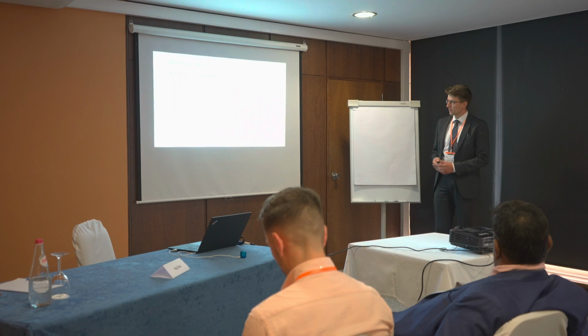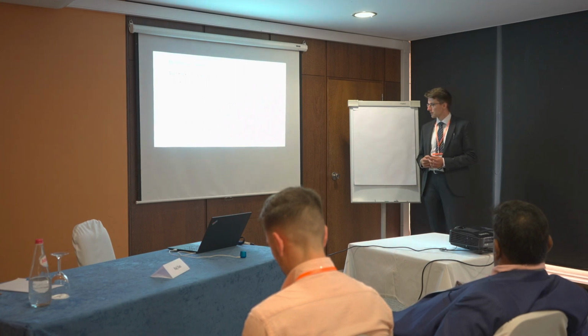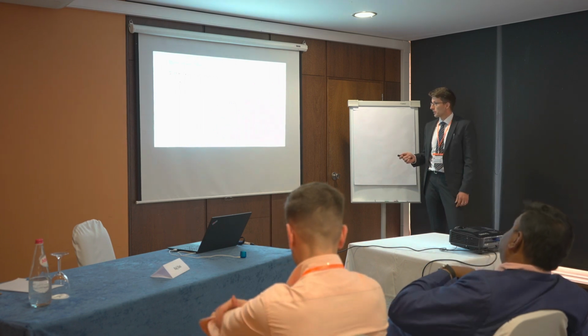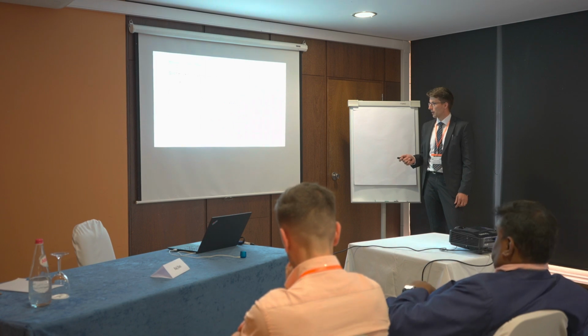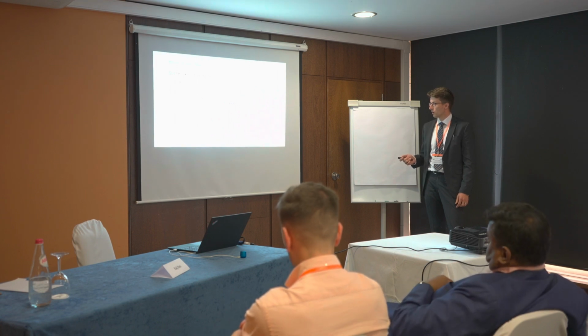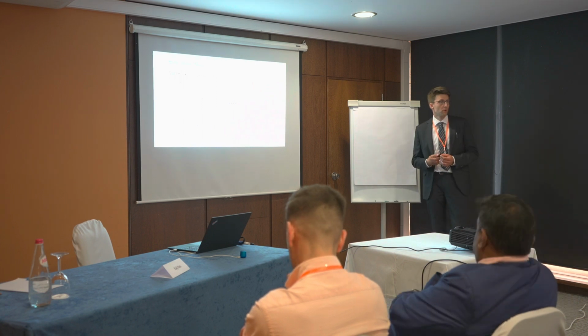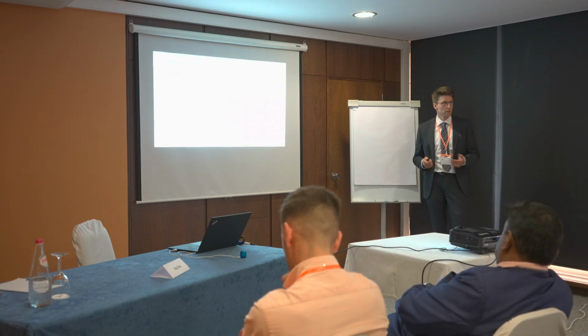This is called the incident pulse, going through the incident bar, and this pulse is partially reflected to a reflected pulse. This is a tensile pulse, and partially transmitted in the transmitted bar. And so we have two displacements, U1 and U2. And of course, if we perform a compressive test, U1 is larger than U2.